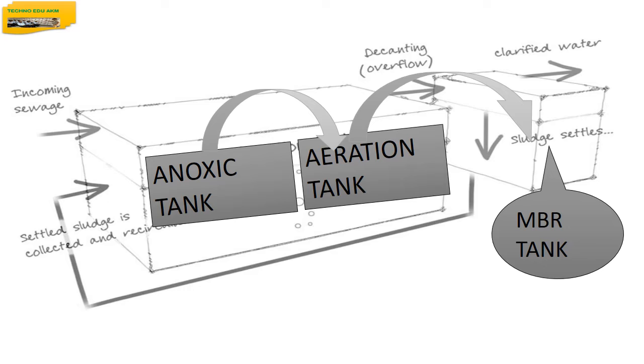During closing of operation of the centrifuge, do the following steps. First, stop the feeding of slurry, so switch off the centrifuge feed pump, then start feeding fresh water. After a few minutes, stop the dosing of polyelectrolyte. Feed fresh water and get the clear centrate.